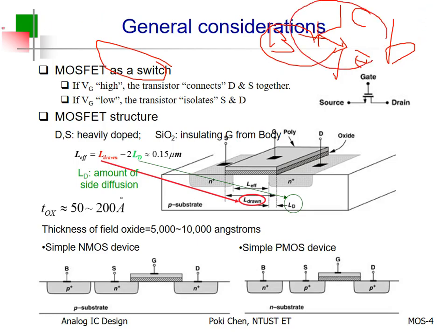And if you focus on this MOSFET, yeah, metal oxide semiconductor field effect transistor. Wow. Okay, that's it. MOSFET. As a switch, again, it looks like this. The current flows from source to drain or drain to source, again depending on N-type MOSFET or P-type MOSFET.